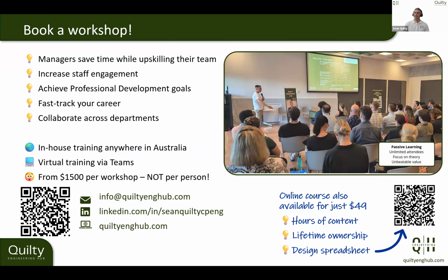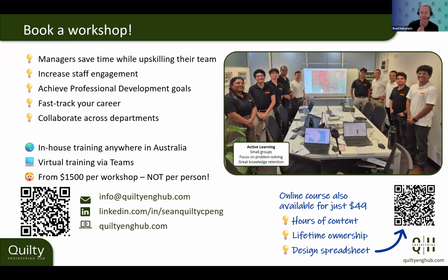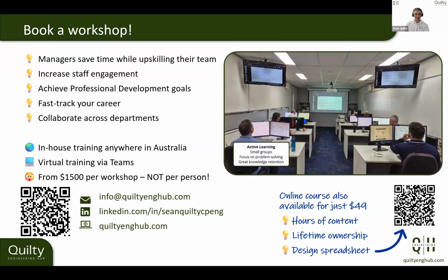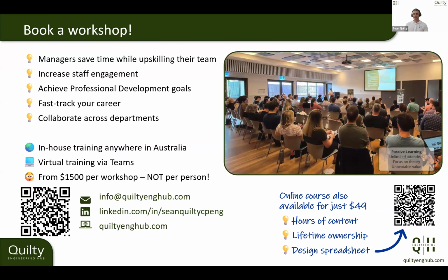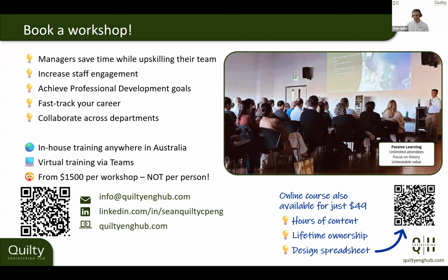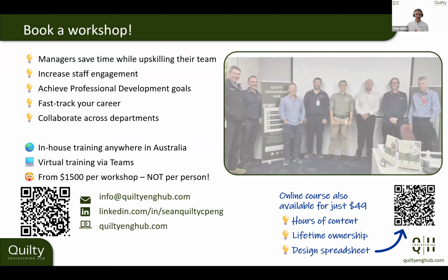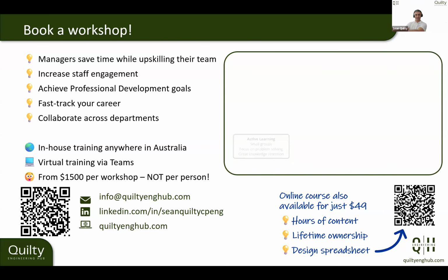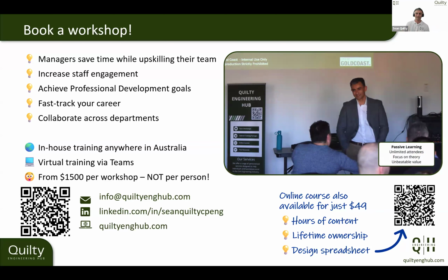So, the design strategies. If I'm answering this correctly, and we could probably talk for half a day on this, I think there's a couple of things to think about when it comes to stormwater management and a design strategy, if you like. As soon as I get any sort of concept design, I will always look at a quick, fast approximation of what's happening, and then try to gauge what the worst case is. For example, if you were looking at a subdivision, and they're going to have pits and pipes, and you're going to have roads that will essentially act as an open channel, and you've got to get the water from your catchment down to, say, a river or something where you're discharging to.